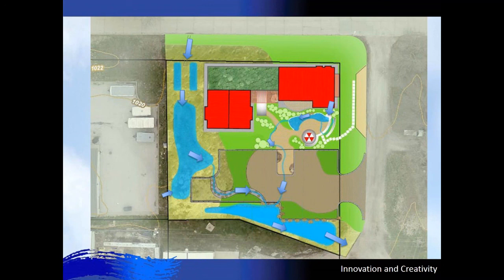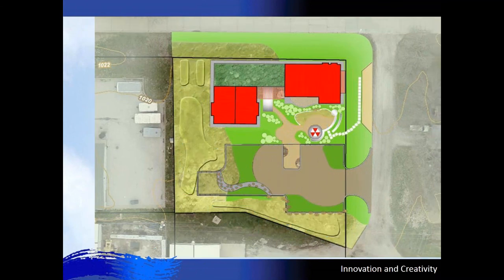The one on the left would include taking the runoff from the road and treating it within a pocket wetland on the side there, and then draining it through the parking lot towards the bottom there. And then the other stormwater pathway would be taking roof runoff, putting it into a cistern, then into the overflow, going into a bioretention cell, and then through several runnels. This is just expanding what creativity could look like within a site.